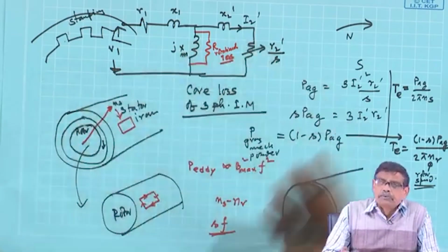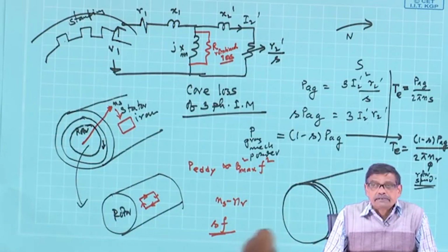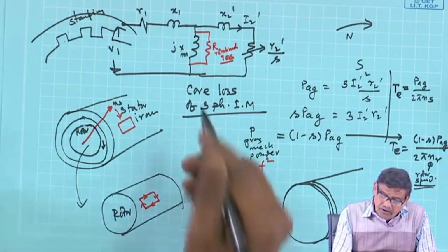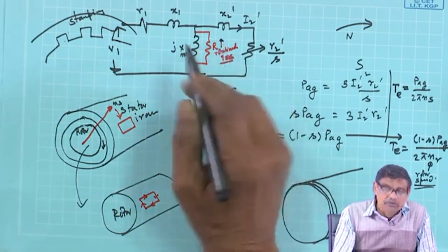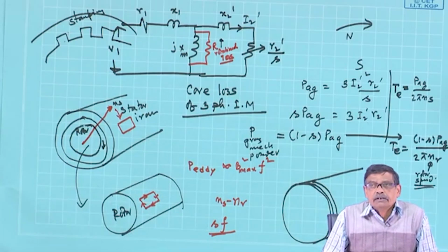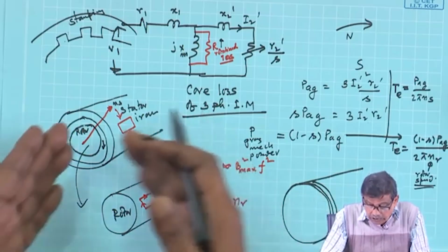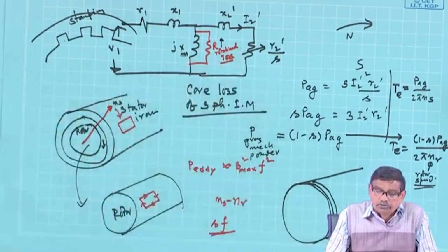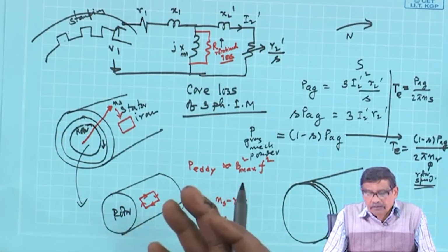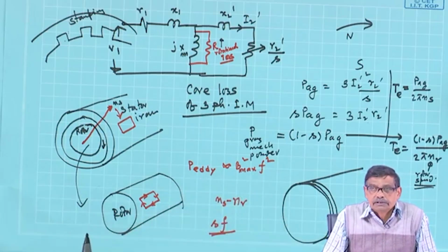So, stator is to be definitely laminated, thin plates, to reduce the eddy current loss. You try to reduce the rotational loss as far as practicable by using stampings while constructing the stator iron. It is not a solid block of iron. If you use a solid block of iron, iron will become too heated up because of eddy current losses.